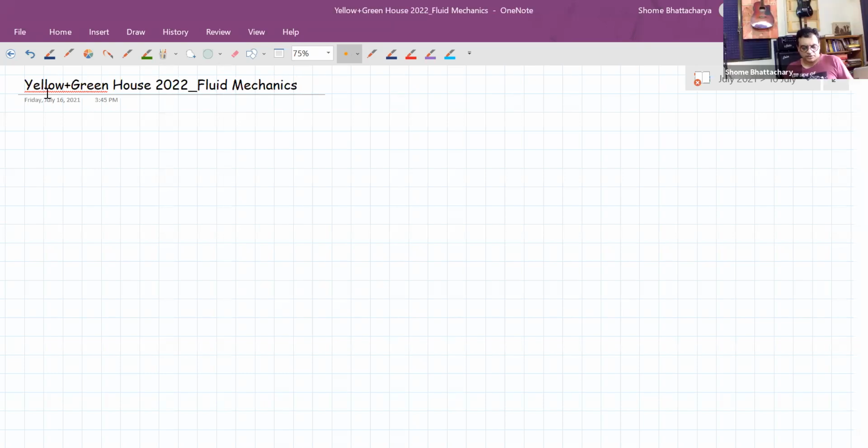Right. So the last thing we had discussed in the previous lecture was the application of Bernoulli's equation in a situation where you have variable cross-sectional area of a vertical pipe. So the pressure difference is affected by the difference in kinetic head because of the area being different, so continuity equation, as well as the difference in the gravity head because it's a vertical pipe. So let's look at further applications of the same.